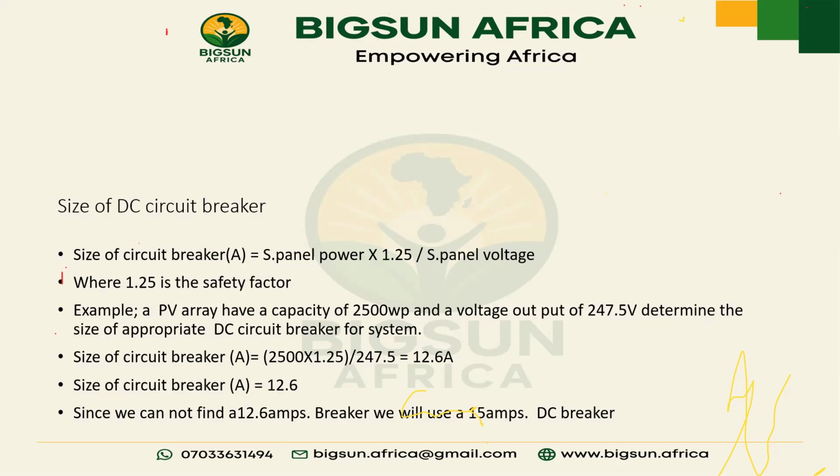It's the VOC you are going to be calculating, but if we have 5 panels and the VOC of one is 49, you are not going to say that your total voltage is 49. It has to depend on whether you are connecting them in series or in parallel. Is that clear?